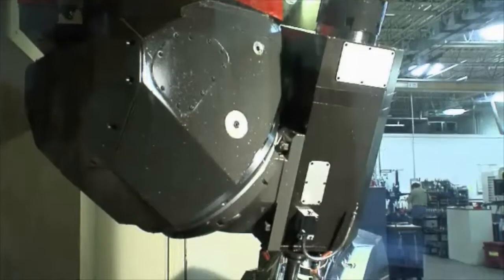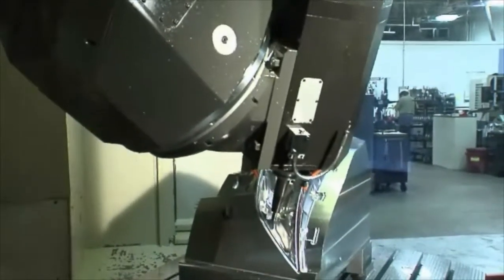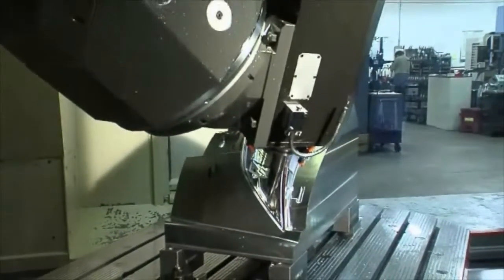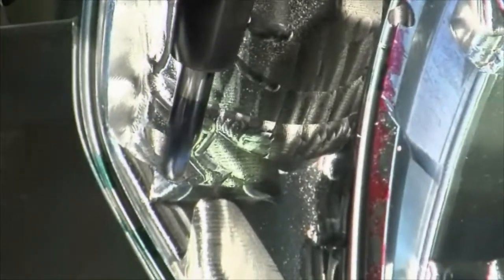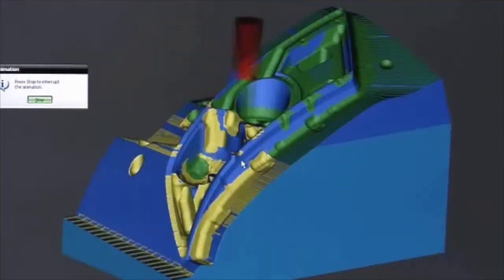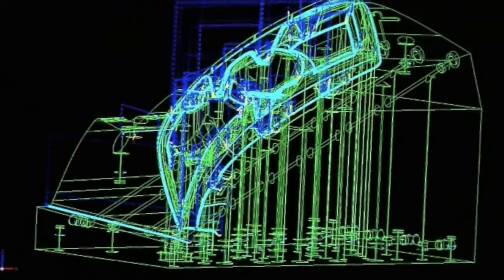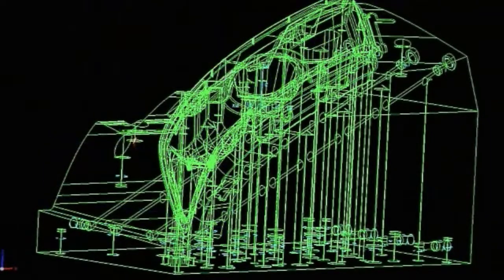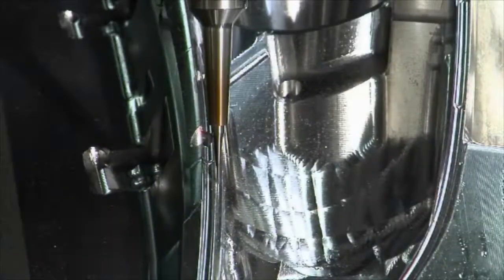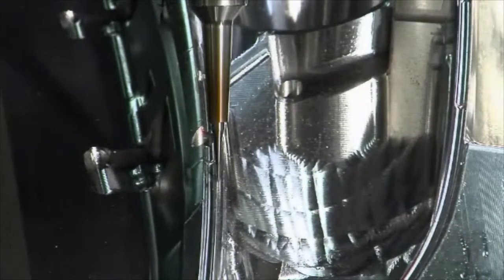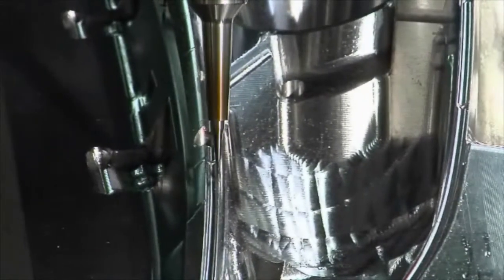You've got to save time, you've got to save money, so we implement high-speed machining whenever possible: small cuts, light cuts at fast feed rates. And yes, NX has several options that you can adjust your paths accordingly. There's options in NX that will actually turn the corners, which creates a much nicer and smoother path. It doesn't have the jerkiness of the machine. It's faster, it's better quality. Now you just set it up and away you go.